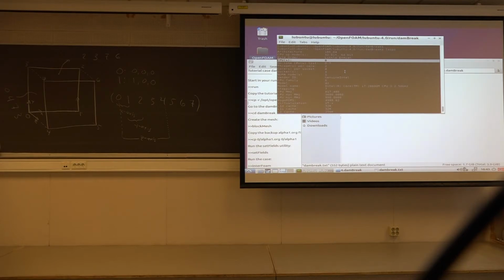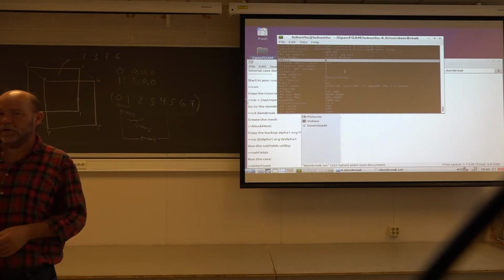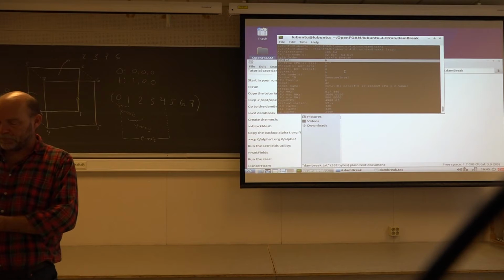What did you write? lscpu in one word. 4, yeah, it's a cheap one. So it depends on the hardware, how it's organized, how many cores you have, how many threads you have, and what they call it. But this is the number of CPUs that OpenFOAM can actually access. So I can split a case in 8 parts and use 8 CPUs. Then hopefully the total simulation time should go down substantially. That's the philosophy here.